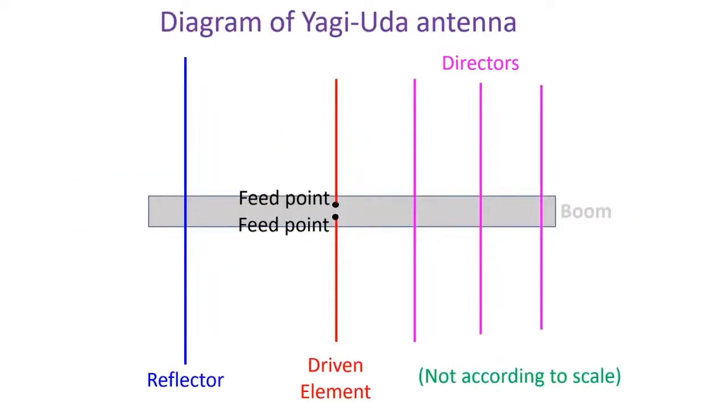The driven element or radiator can be a simple dipole with two quarter wavelength rods connected to either conductors of the feed line. In some versions, it is a folded dipole which has a higher impedance of around 280 ohms. The television antennas of yesteryears with folded dipole used to be fed using a twin lead transmission line with impedance of about 300 ohms. Folded dipole will need a matching for amateur radios with impedance of 50 ohms. Usual dipole has an impedance of around 70 ohms.